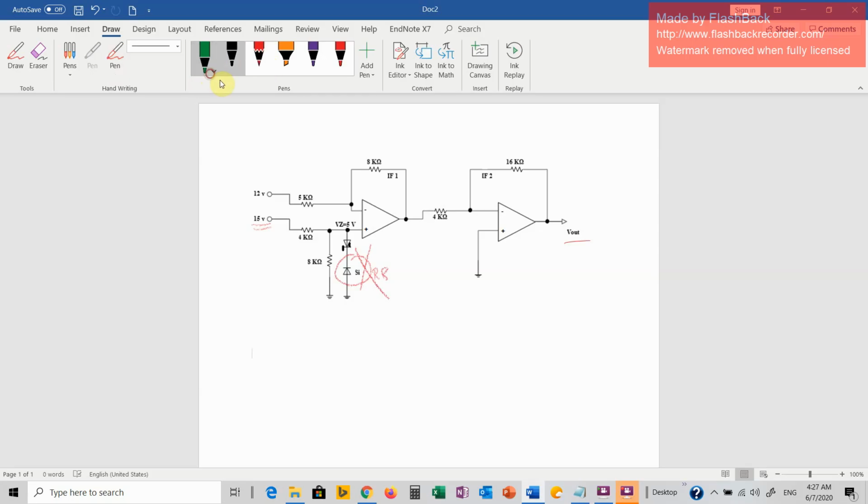So now again I_P is equal to I_N and it's equal to 0, and V_P is equal to V_N. So the current here is equal to 0, and same here. That also leaves the voltage at this point equal to the voltage at this point. Now I'm looking for V out, so it's a good idea to find V out 1, let me call it here.